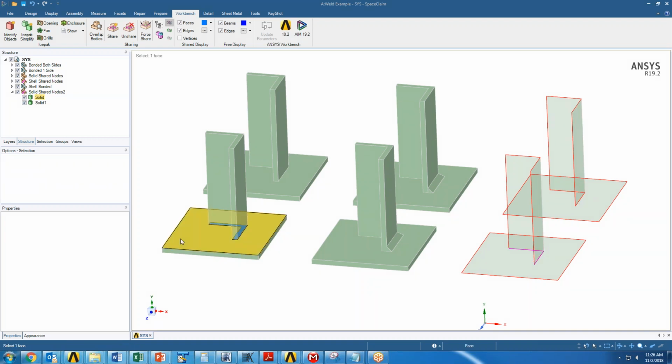So you have a lot of options in terms of how you want to represent welds. Based on ease, based on safety and quickness, we almost always go with, as long as the bodies in an assembly are the right thickness, the width to length ratio, and they can be shelled accurately, we'll always pretty much go with the approach to the bottom right, which is extracting surface bodies and then joining surface bodies with shared topology and shared nodes wherever welds occur.